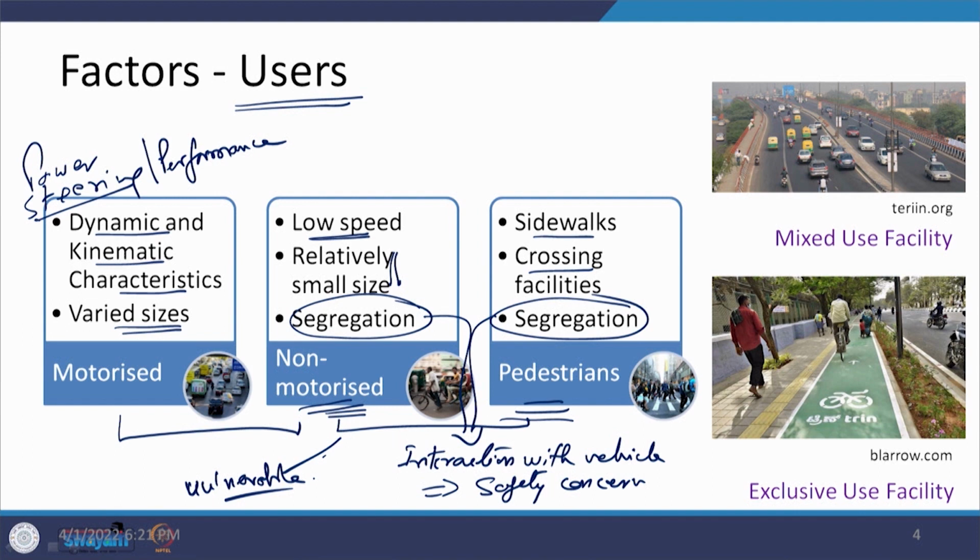When you look at the photographs which have been made available on the side, what you can see is that in the first one the whole of the carriageway is being utilized by n types of vehicles. So, there is no such segregation which says that such type of vehicle is to move in a particular lane, though a footpath may have been provided at the side, or a cycle track may be provided at the side, which can be utilized by those specific users.